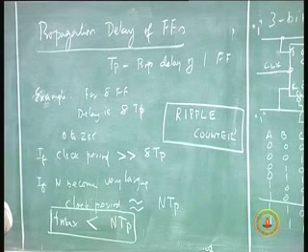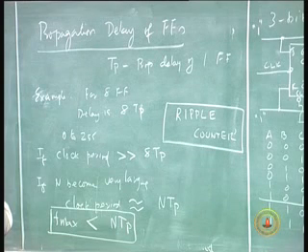A synchronous counter in principle will take care of this problem. The ripple counter suffers from the problem of too many stages and propagation delay affecting the total number of counts I can use it for.